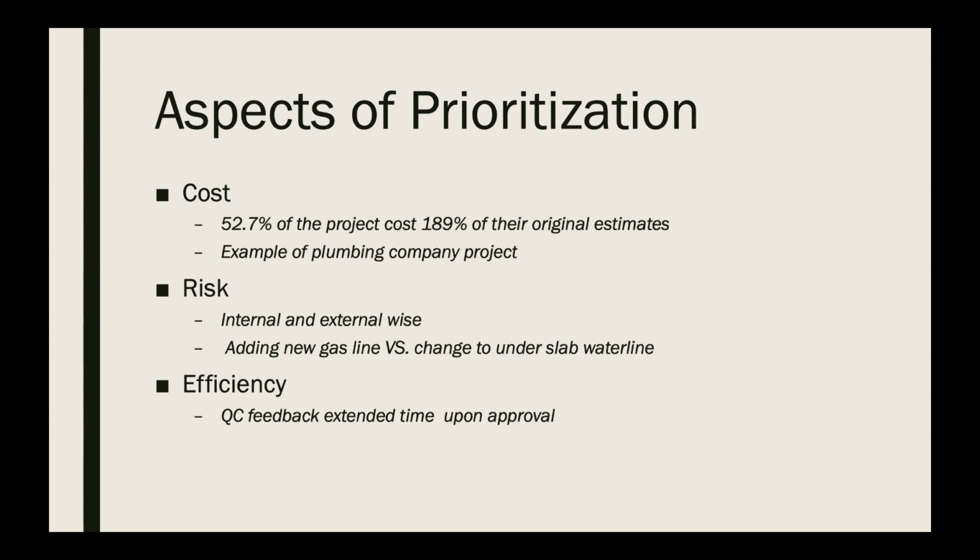my responsibility is designing the water lines part in the plumbing system in a house. Based on the city's requirements, I need to draw the routes for hot and cold water to feed each plumbing feature from the main water line from the city to each feature in a house. The original way of doing this is, after connecting to the main water line, water pipes will be brought up to the attic, then dropped down to each plumbing feature.